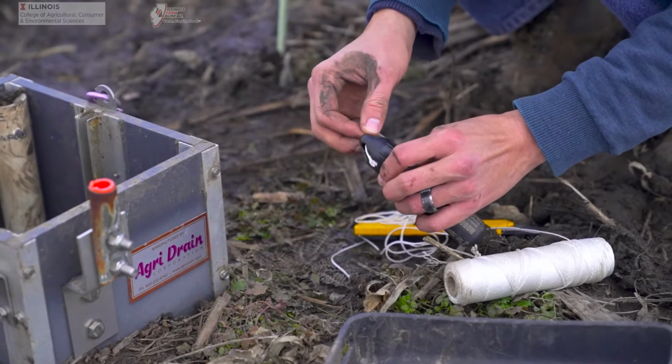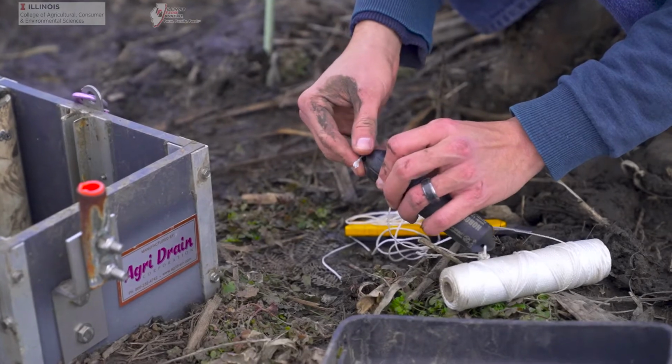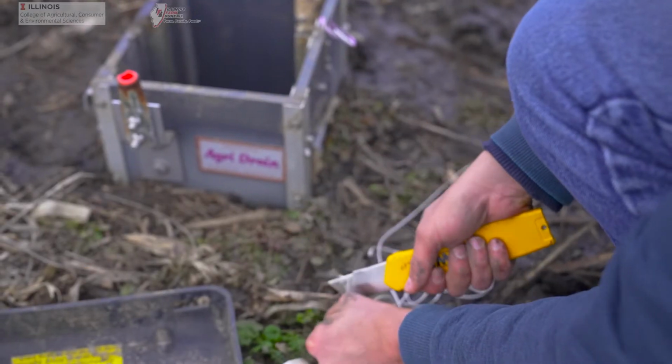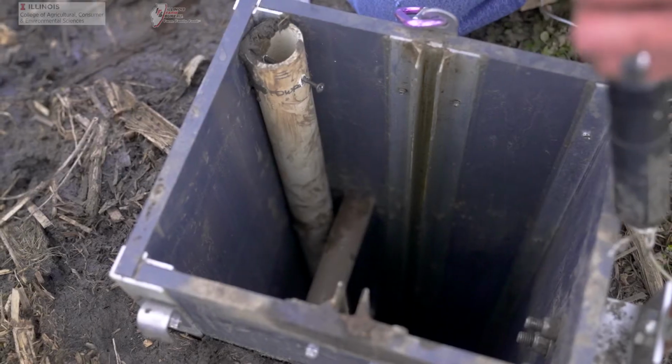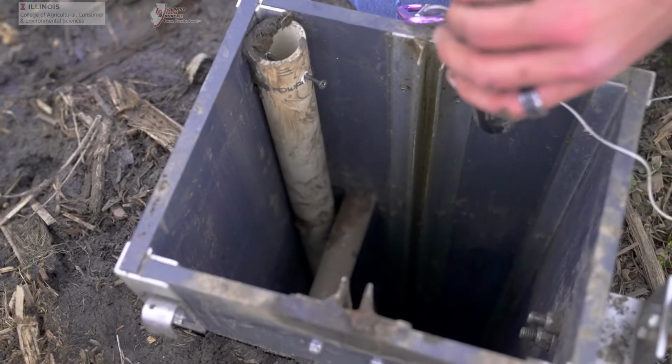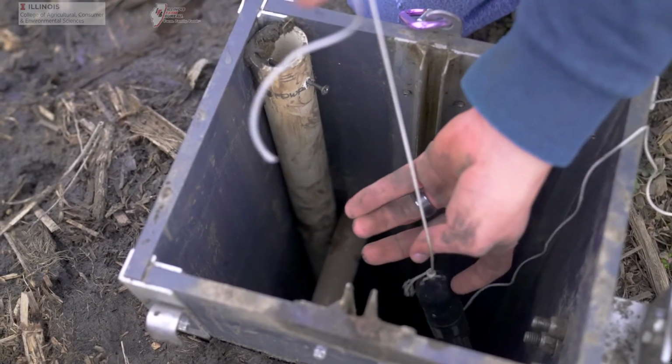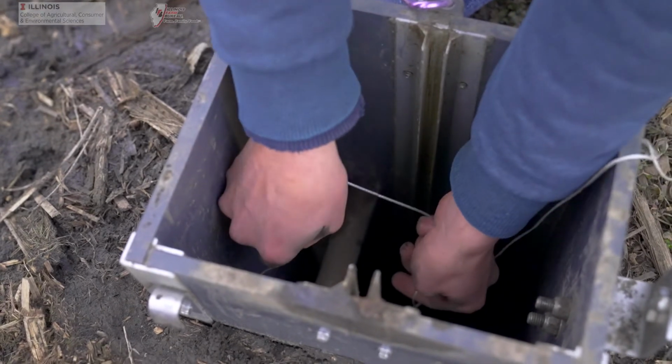The relatively inexpensive water depth sensors we use to monitor water flow rates are essentially just recording pressure pushing down on them, so we have to record the fluctuations in barometric pressure simultaneously so we can remove those pressure changes from the logged water data later.